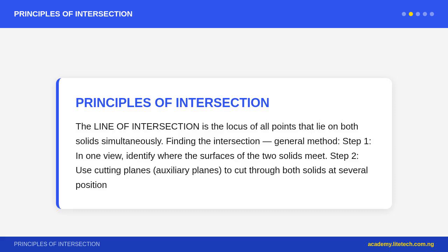Case 1. Two rectangular prisms meeting, for example a T-junction of two square tubes. Given, a horizontal square prism penetrated by a vertical square prism, smaller. The intersection consists of the outline of the smaller prism's cross-section, projected onto the surface of the larger prism.